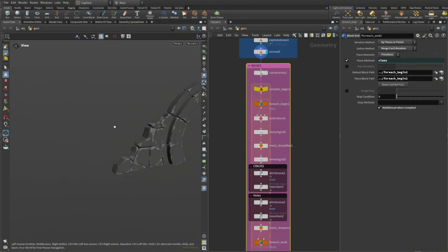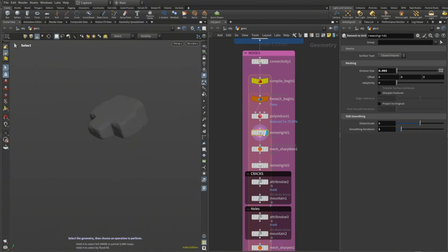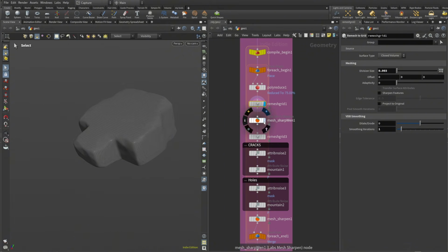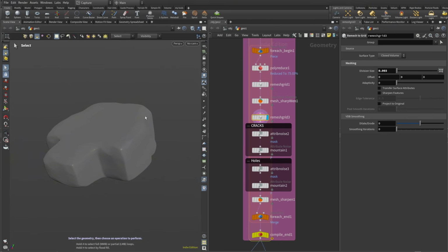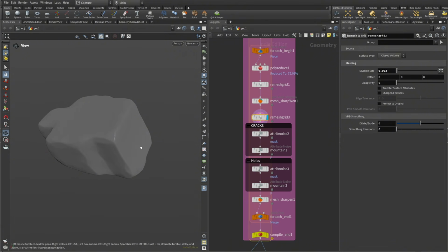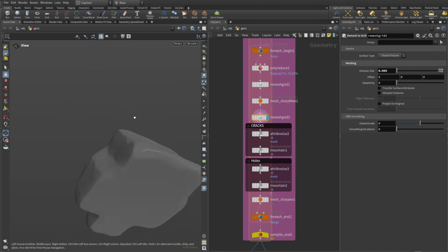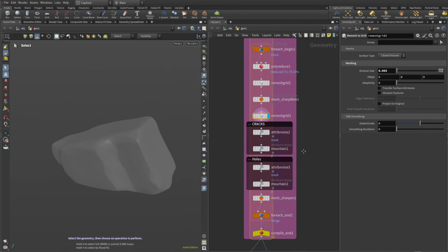So we will start with a bit of optimization. We just simply poly reduce a bit and then make a remesh grid. This way I voxelize and sharpen to make this base shape, and remesh again to smooth the result a bit. Otherwise the polygons, the triangles, will be very visible, so by doing this you basically erode the underlying mesh. So now we have something a bit more natural, and then we process into two noise paths.